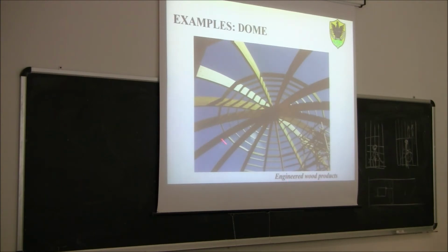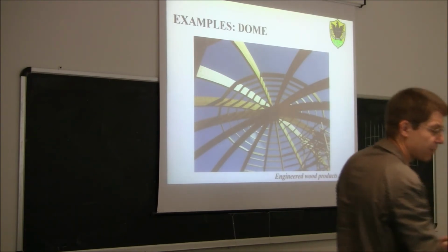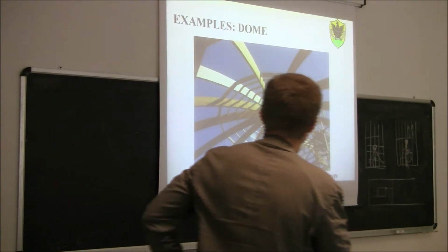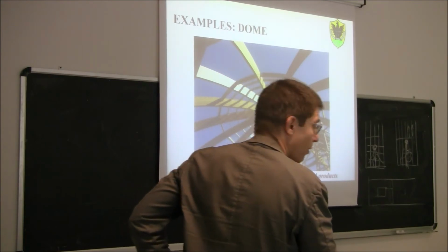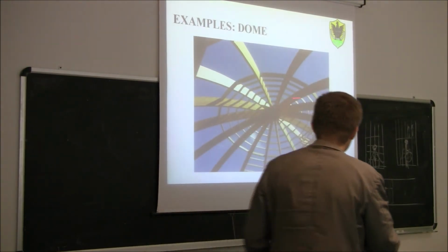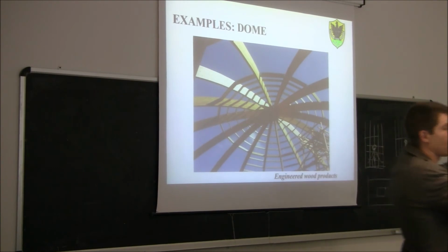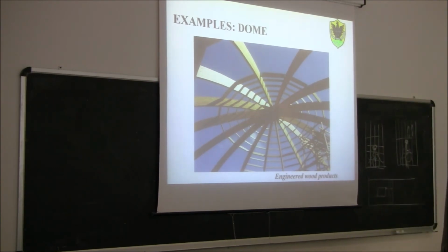Then you have these other elements, the top ones subjected to compression and the lower ones subjected to tension. Of course, one problem is that all these arches should converge to the same point. The problem is that these arches are not very slender, they have quite a big cross section, and so there is no room to get all the arches in the same point.